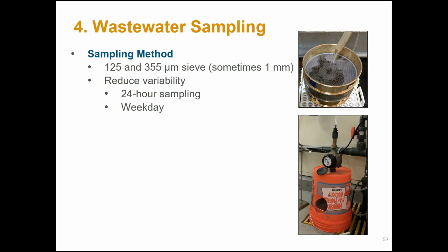In order to reduce the variability in our sampling, we took 24-hour samples, so the effluent flow was allowed to flow for a period of 24 hours.